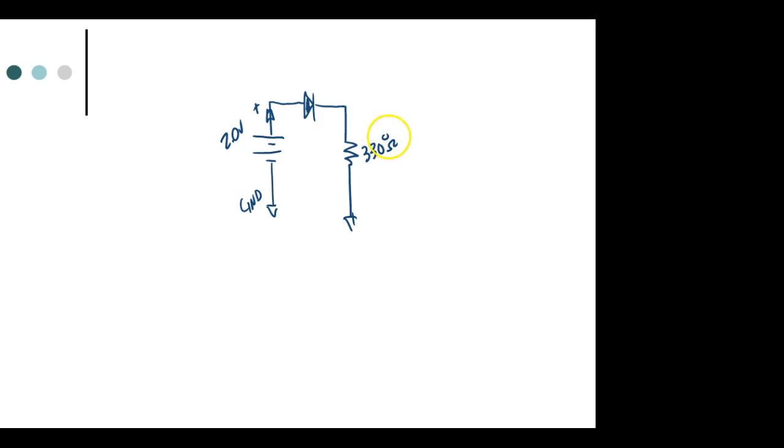What's the color code for 330 ohm? Most people say black. That's wrong. Black means I add no zeros. We got to add 1 zero. People see that black and they say, well, black's equal to 0 and I need a 0. But remember, that number is the number of zeros you're going to stick out there. So black says I'm going to put 0 zeros, right? How many do we need to put? Need to put 1. So it's going to be orange, orange, brown, right?